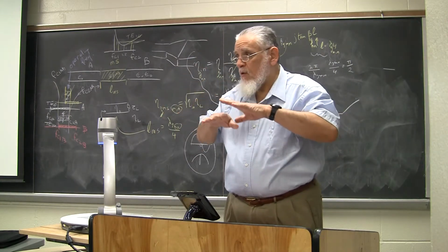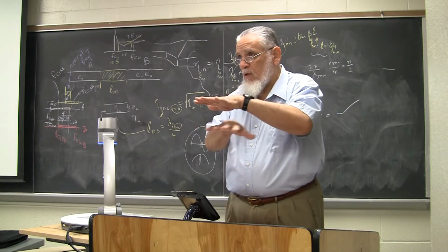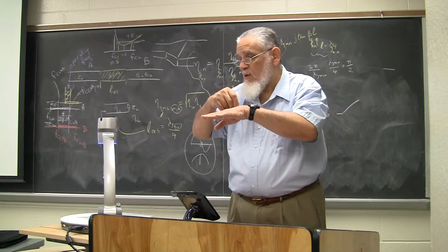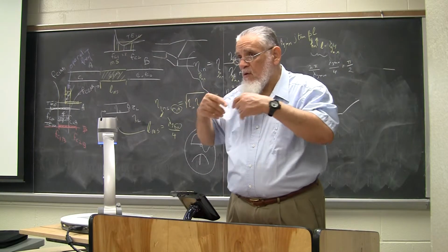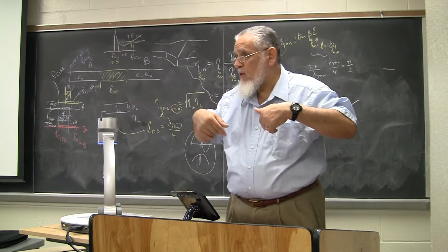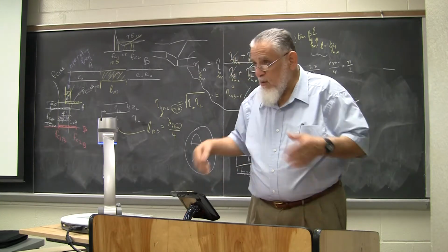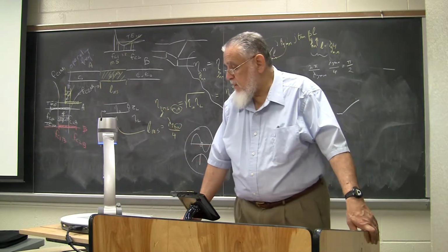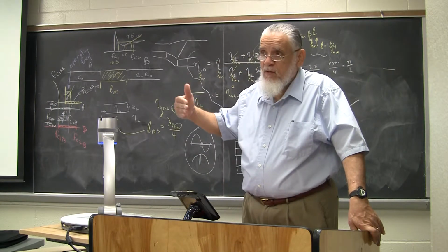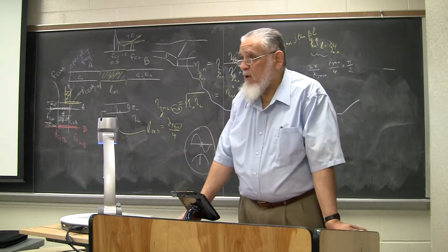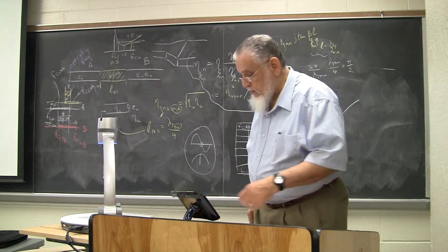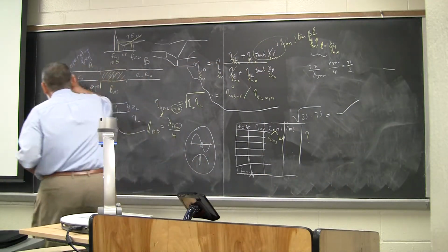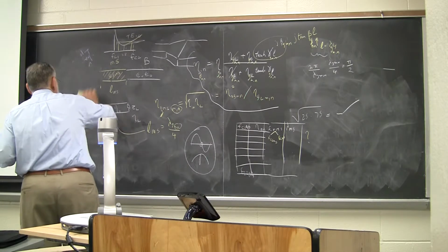Going through the dielectric insulation between the conductor sheets, we make vertical holes and fill those with conductors, and those vias are going to be an array. You can space them as closely as you like, but obviously their location determines the behavior of the whole circuit, because those vias are not going to be perfect, and they will cause issues.